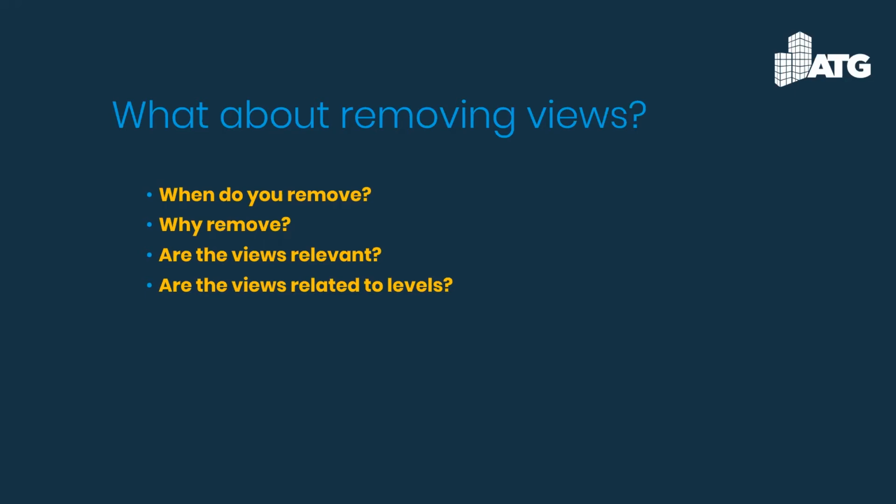I was asked a question about just having more views. Does it increase the file size? It's going to increase the file size depending upon what you have within that view. Going back to that 3D view, if you're showing a 3D view, you're showing a lot of geometry within that 3D view. So that's what eats at the file size.